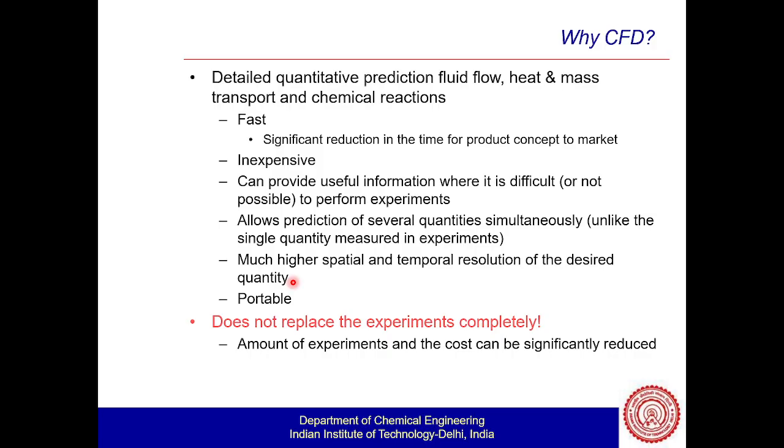So it doesn't replace the experiments completely. The CFD models you are creating should be validated by the experimental data. So the model is giving you a temperature or a velocity profile, and that should be validated by experiments. The experiment should agree with your simulations.